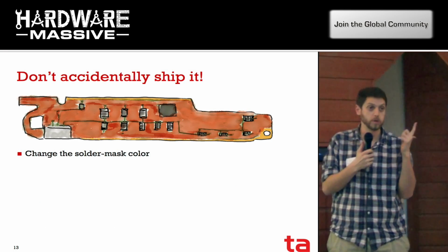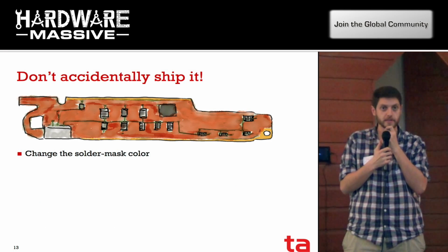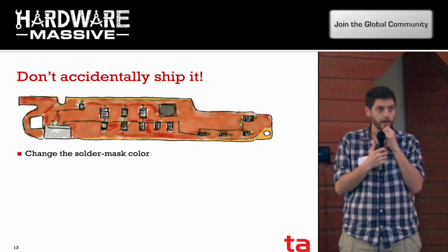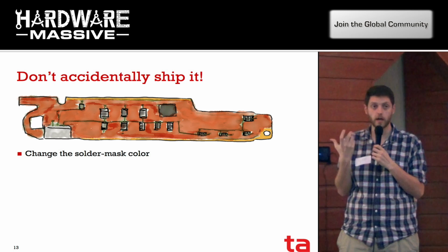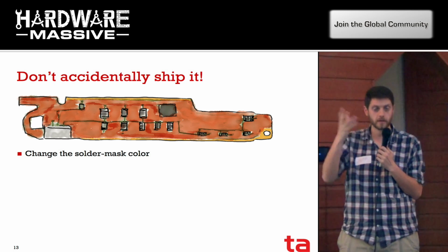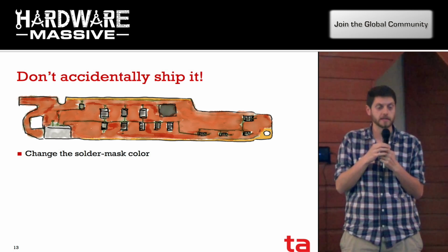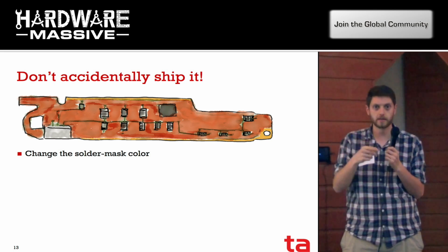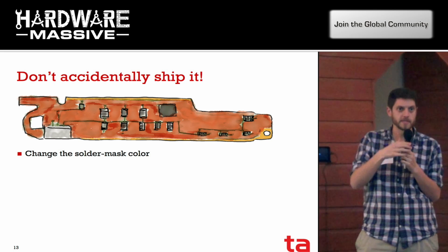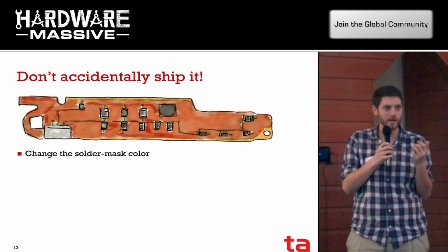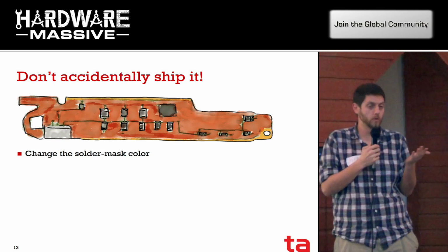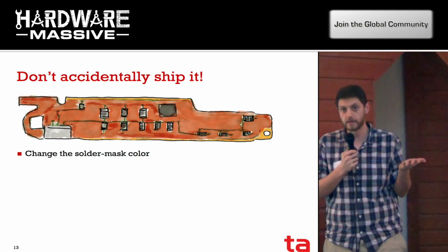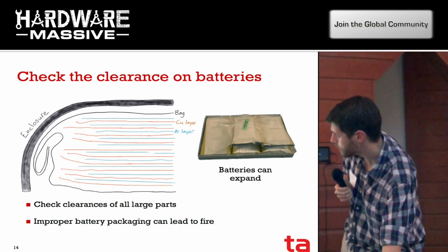I think one blunder that can come with this pattern is making sure you're deliberate about the solder mask color for the board. In my experience it helps a lot to have a different solder mask color for these prototype fake ones. So it isn't like, oh, this is out in the field, or, oh, we're trying to put this together for a prototype to send out to customers and it doesn't quite work. To have it just glaringly obvious what isn't real is definitely a value.